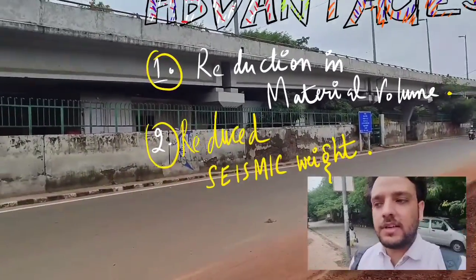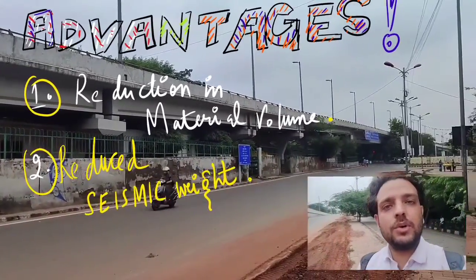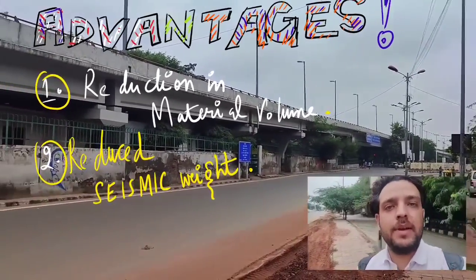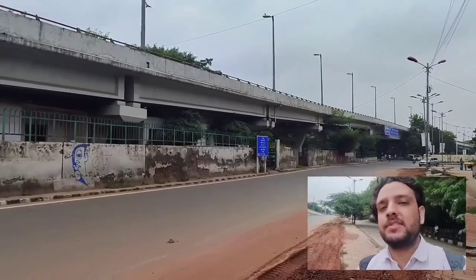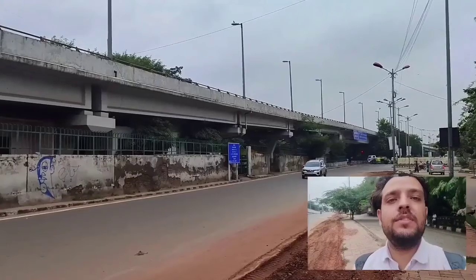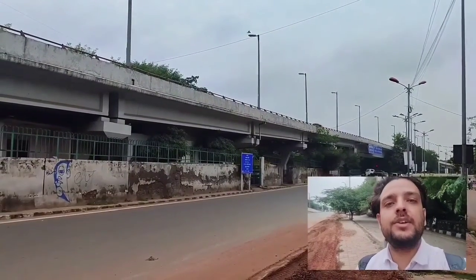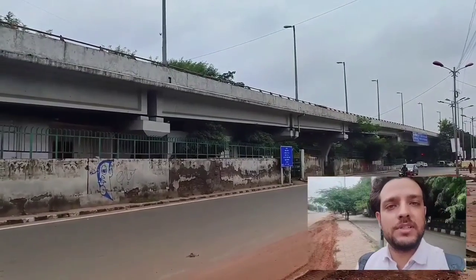Now we will discuss the criteria based on which the total number of girders and the spacing between them is decided. First of all, the major factor is the total carriageway width that the structure is intended to support, which defines the number of girders you must keep.